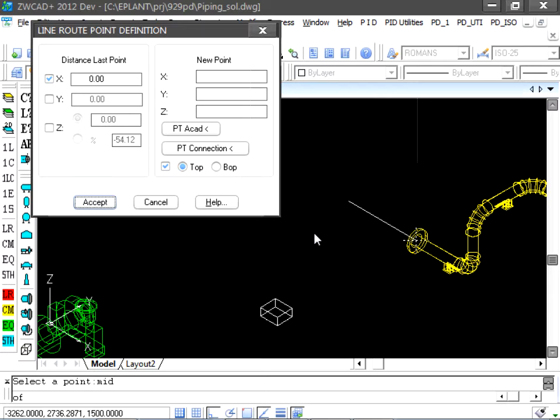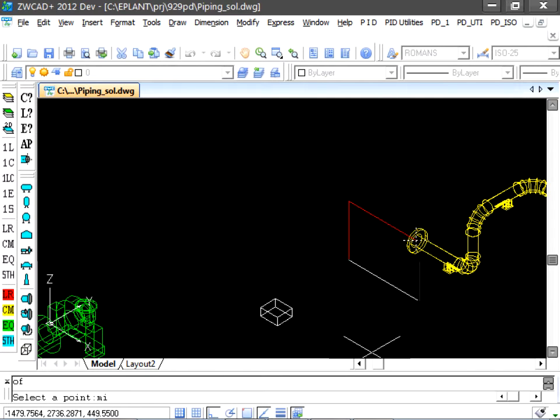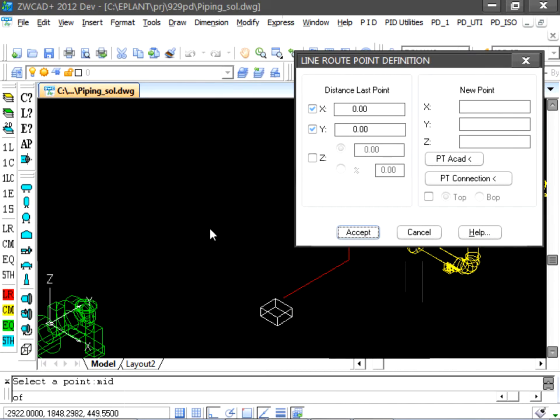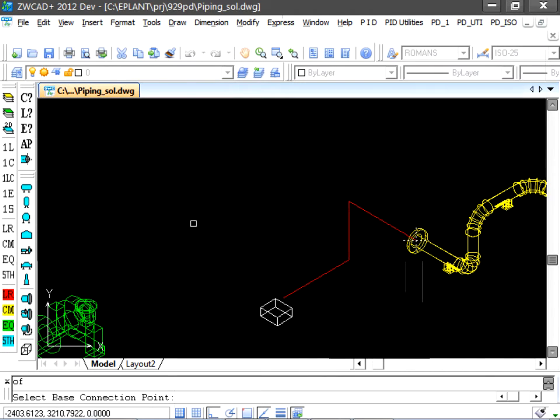We are going to do the same but moving down along Z. And the vertical segment is also created. Now we are going to move along the y-axis. The pipe placed on this center line will exactly lie over the upper face of the block. We can now finish the remaining segments up to the nozzle that will be selected by its connection point, forcing the path to follow the coordinate axis.